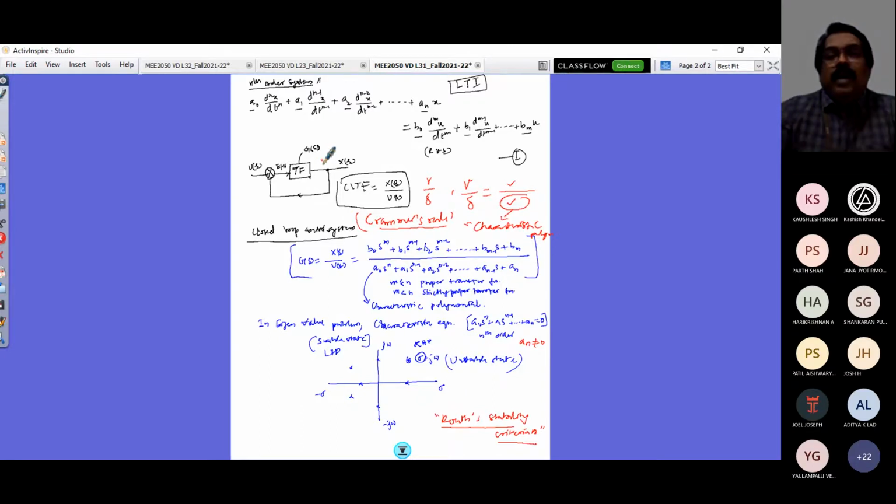We were able to get the transfer function here, what is called the closed loop transfer function, for a simple bicycle model by Cramer's rule. If it is really an nth order system, the closed loop transfer function can be a ratio of two polynomials, and there we defined the denominator polynomial as the characteristic polynomial. Right. So how do I get the transfer function for this?